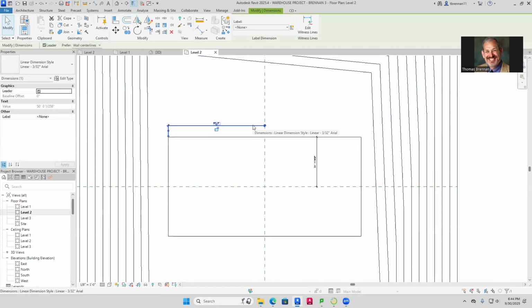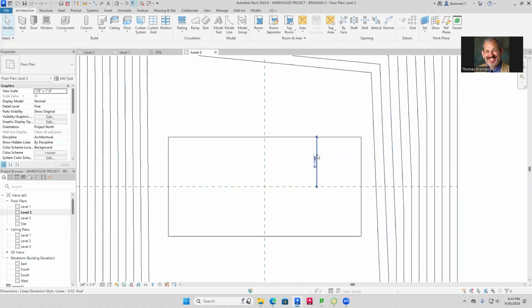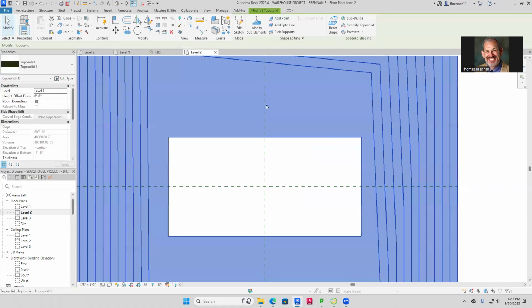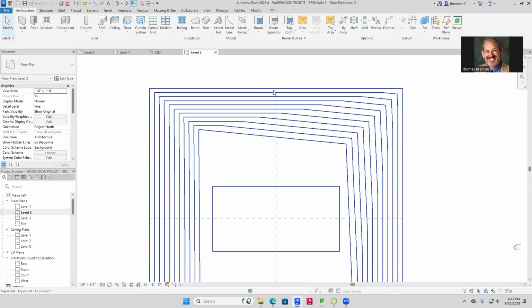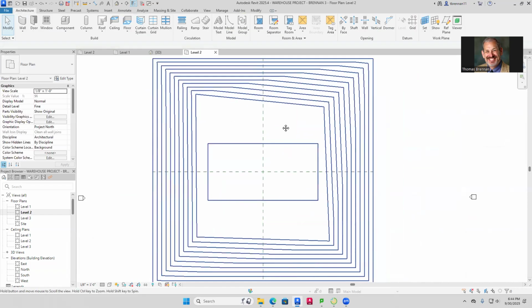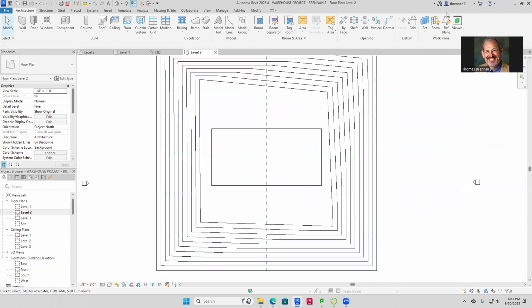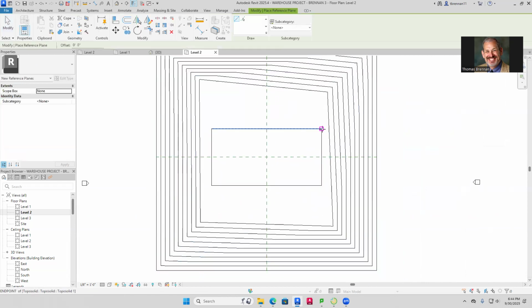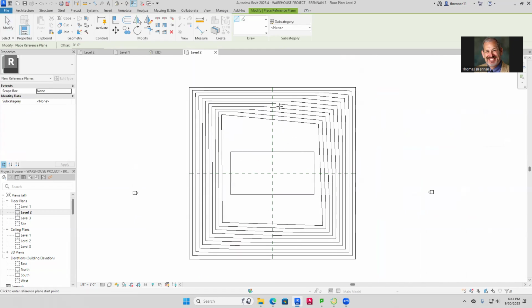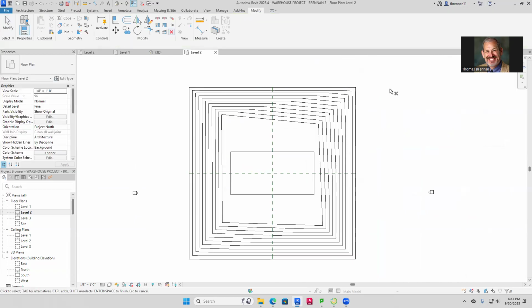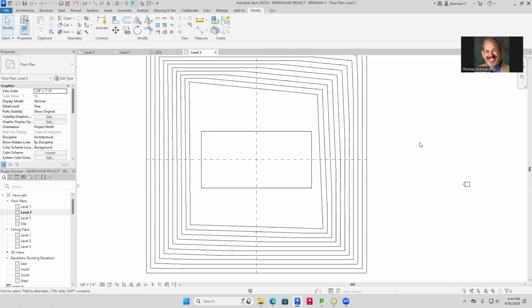And what I would have done probably in that particular case is I would have made these reference planes. I would have just offset those, and then we could have just used the align like was just suggested. So let me go ahead and go over here. What I can do here is touch this reference plane over. I'm going to go over 50 feet, like that. Actually, I'll just count. Well, you get the idea though, right? Does that make sense, Mike? Okay. So once you've got that, you'll have it dead on.